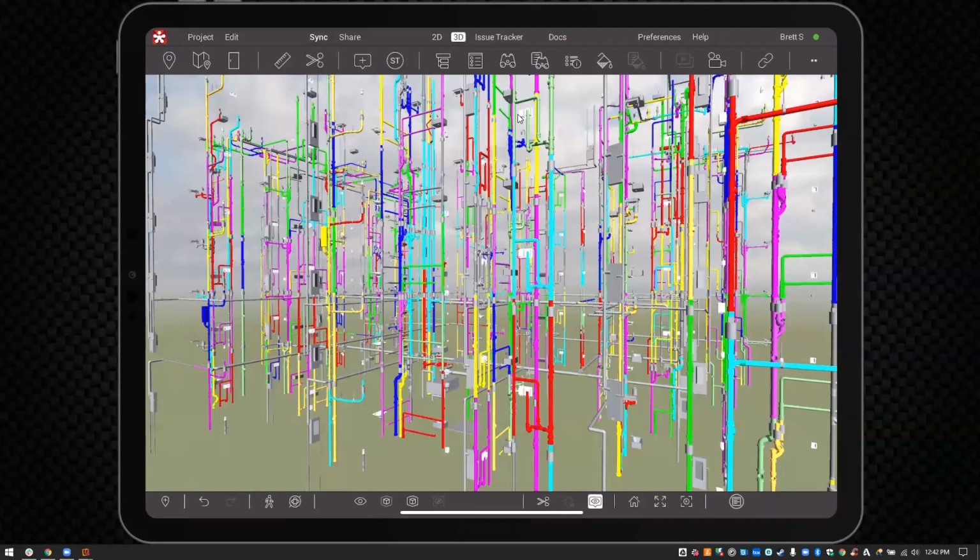The other thing that we didn't show today is the ability to transform models, which is also in Revizto 5. So anybody that's worked with any of our workflows knows that the coordinates have to be correct upon coming in. And it's something that we either do inside of Navisworks or we do inside of Revit. Make sure that everything is coordinated and then we bring it in. But for some individuals, especially on the construction and the MEP side, for people that run coordination, they don't always have that opportunity.